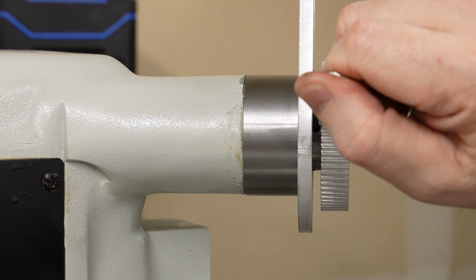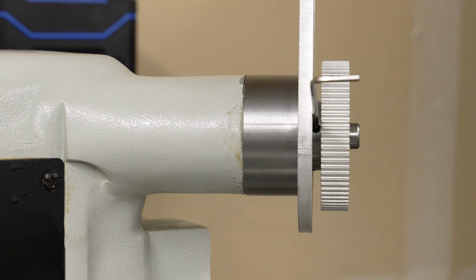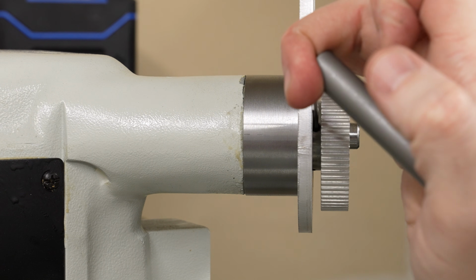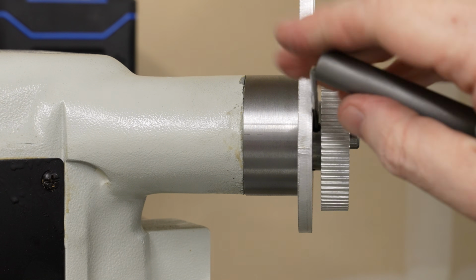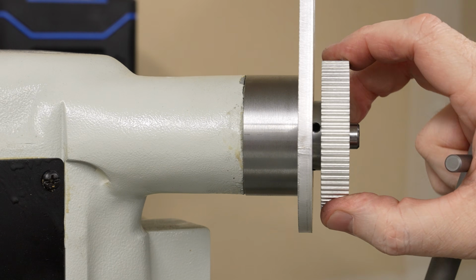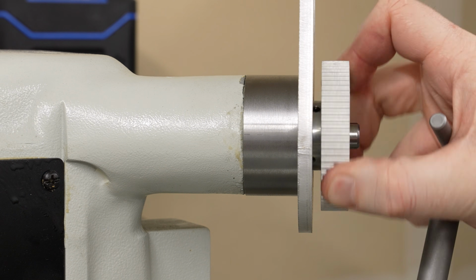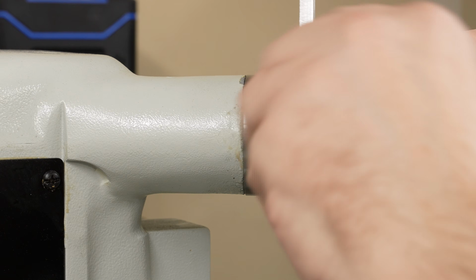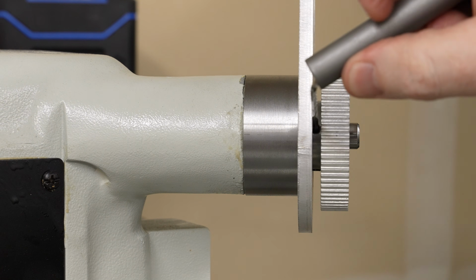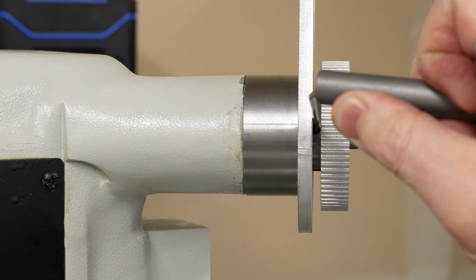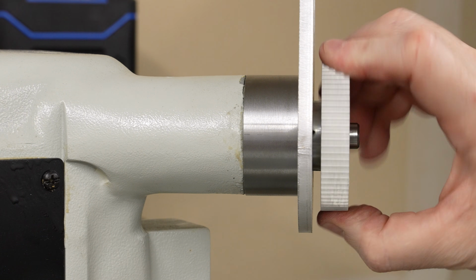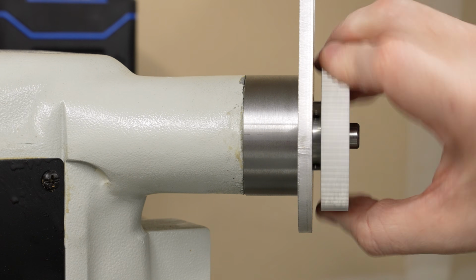And because I'm having to use the short handle of the wrench to turn this, I need to get something to apply a little bit of torque. Found a little T-handle wrench here with a hollow handle or a hollow shaft. And we'll give that a little bit of a turn. And then we'll tighten the other one just as well. So these are cup point screws, so they should bite into the shaft on that reduced diameter portion. I just want to make sure that that will actually happen. So I'm giving these about a quarter turn once they're tight. So it's actually winding up the wrench, between an eighth and a quarter of a turn of spring.